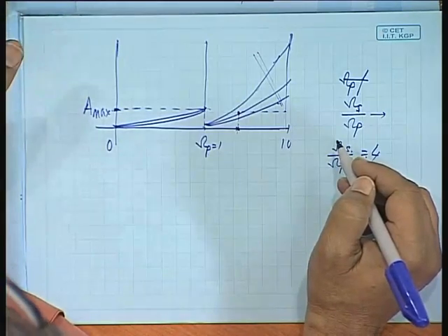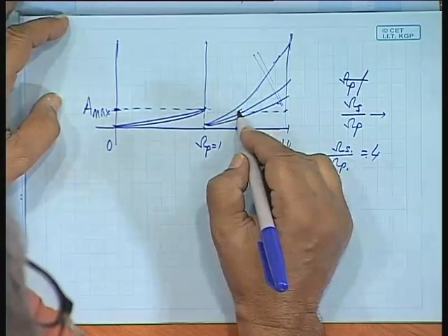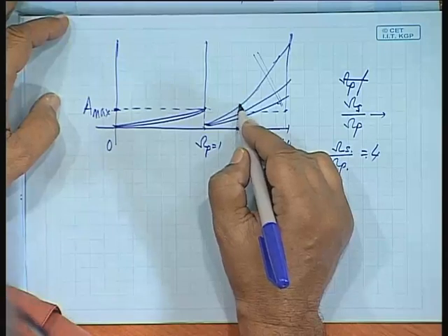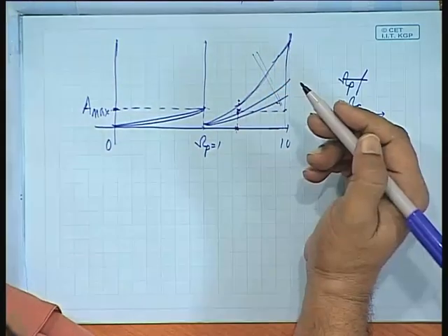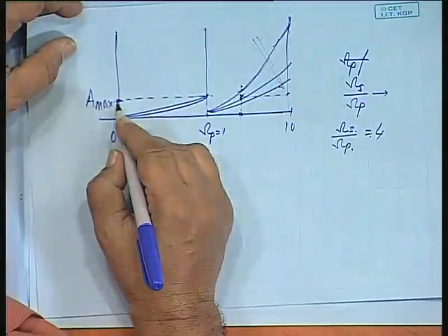If A minimum is specified, I will just refer to the nearest integer value, I will go to the higher value next integer. So, I select n. Once you select n, the Butterworth polynomials are fixed. They are all on the unit circle, you know the location of the roots. So, you can calculate the Butterworth polynomial, and even they are also available in the table. So, the design is very simple with the help of such charts for different values of A max.